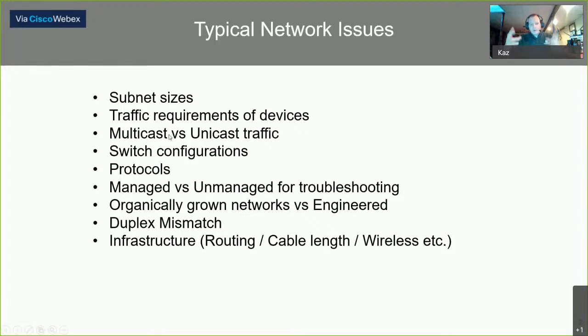So if I have two controllers controlling Ethernet I/O with an RM module, redundancy module between them, that has unicast or multicast traffic for all of its I/O. It has to be set up for multicast just for the failover.